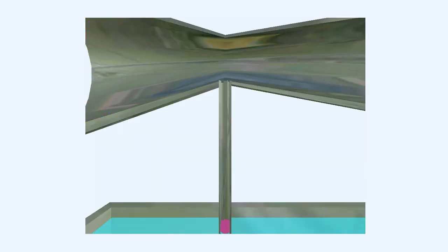A suction applied to a tube immersed in a liquid is sufficient to raise a column of liquid to a certain height up the tube. Should a small hole be made in the tube, under the same conditions, bubbles of air will enter the tube, and the liquid will be drawn up the tube in smaller drops rather than a continuous stream. In other words, the liquid will be diffused or made to intermingle with the air. Air bleeds into the tube and reduces the forces acting on the fuel, reducing the flow of liquid through the tube.